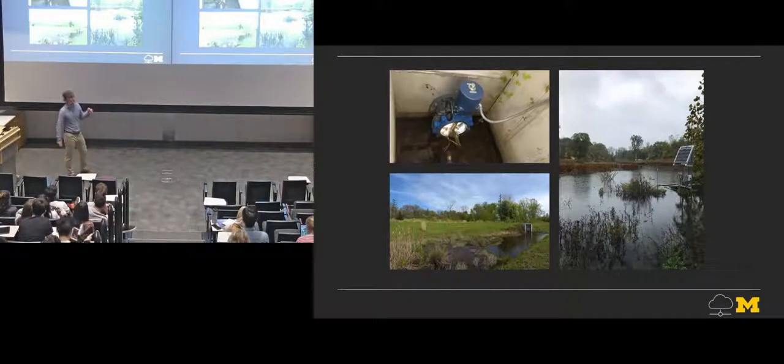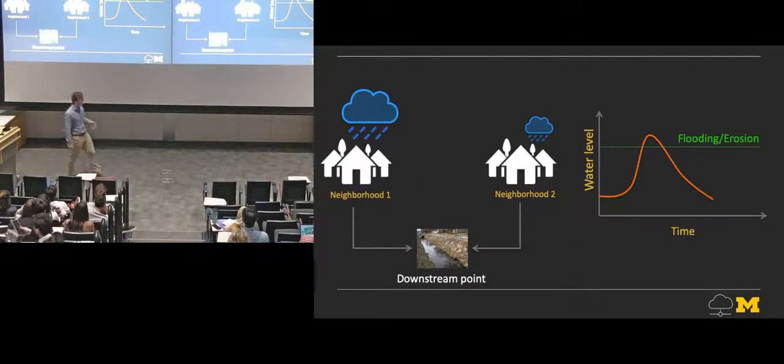And then we just look at the weather forecast and we say, okay, Weather Underground is saying it's about to rain. You just open the valve and let the water out. And then you have storage for the next storm. Okay? And where that becomes really interesting is when you have hundreds of these, okay? Or in this conceptual example, what if I have 2 valves?